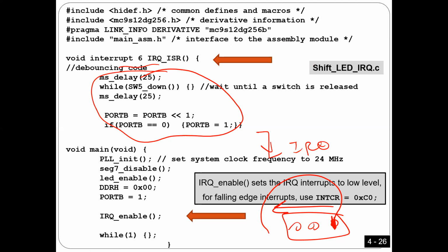You are calling a subroutine, but you don't need to write an instruction to call it, because the subroutine is called automatically when there is an event, as I said before. Anyway, very easy. So in C language, guys, you have to write here just number 6, and then write whatever you want to write here. Okay. And now, how can I configure the IRQ interrupt?